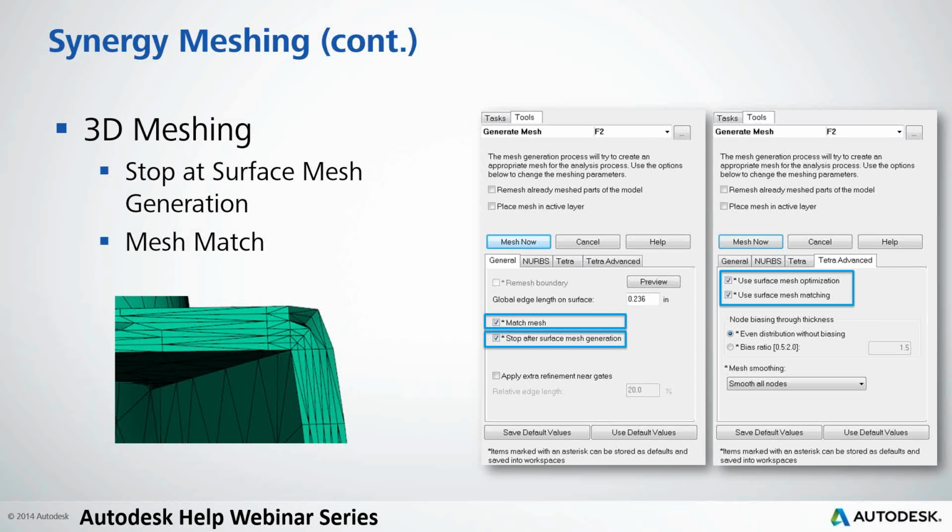And with that, you can take it into the mesh diagnostic tools and look at mesh statistics and everything like that to see if the mesh is actually suitable for meshing to 3D, and fix any issues that you might run into with that surface mesh. That way, when you go to mesh it again as 3D tetrahedral elements, it'll reduce the need for manipulating the 3D mesh after the fact.